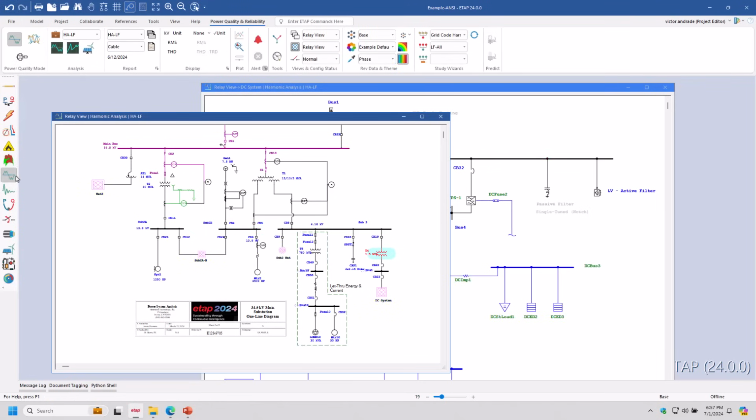So moving on to the next group, you have the power quality. With power quality, you have your harmonics. This would be when you need to comply with the IEEE 519 standard. I think most of you probably are familiar with this module. A pretty new module that was released in 22.5 is the unbalanced harmonics. So remember, anytime you have single phase loads, for example, many EV chargers in large industrial and commercial facilities, then anytime you have single phase loads that introduce harmonics, you have the ability to model that now with the unbalanced harmonics. And then reliability assessment, which also includes techno-economical studies.